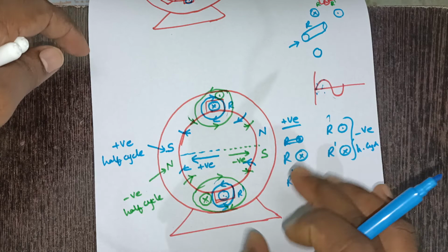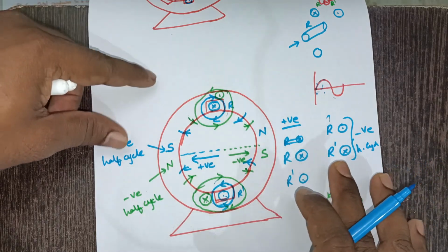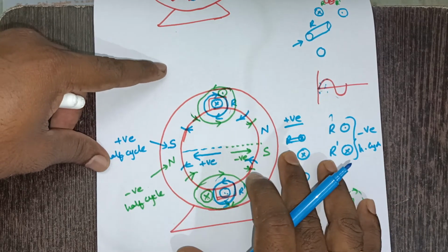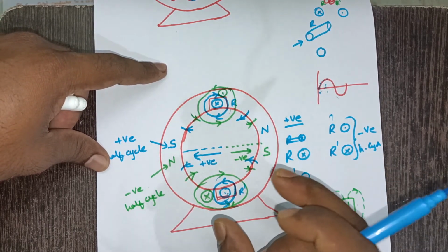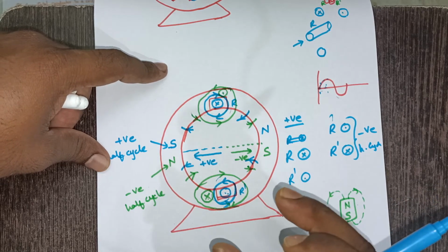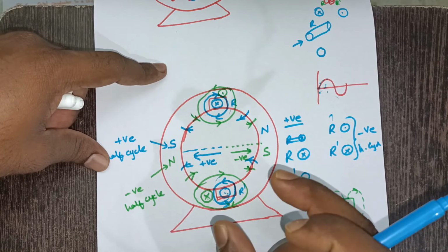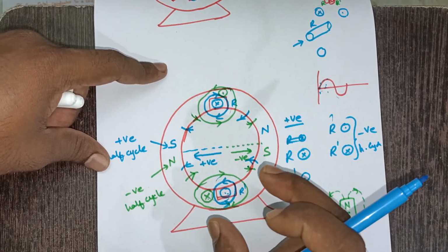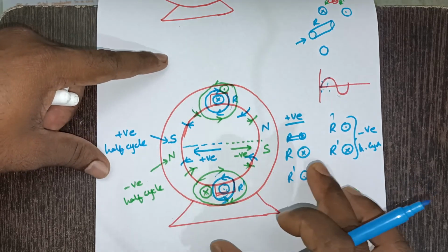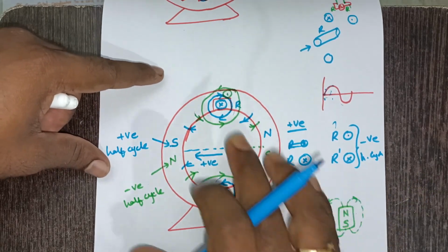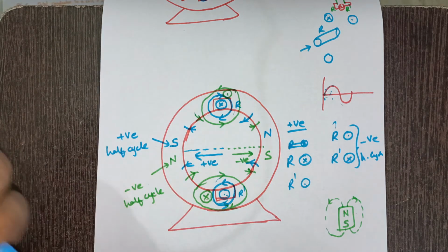Like this, we have to place all the phases, right? Actually, we are discussing three-phase induction machines. In that three-phase induction machine, we need to provide three-phase winding. So before providing that three-phase winding, first we need to understand what exactly happens if we provide a single-phase winding on the stator and give excitation to it. That is what we have seen till now, and from this diagram we need to understand important points.